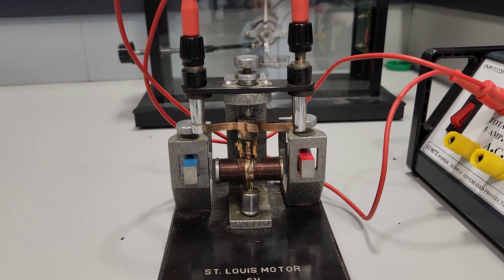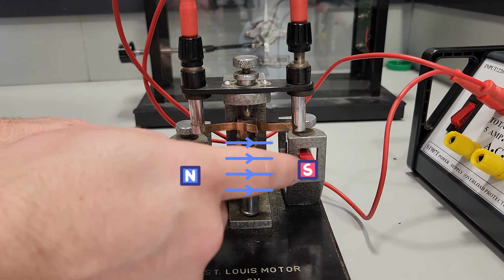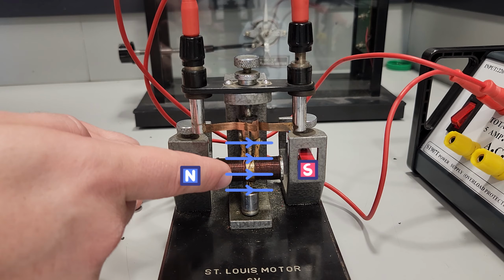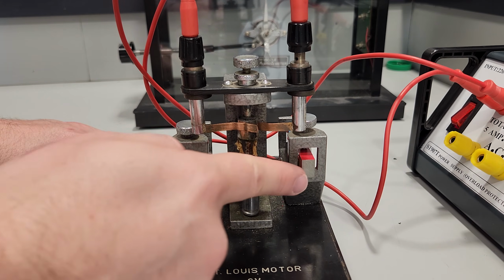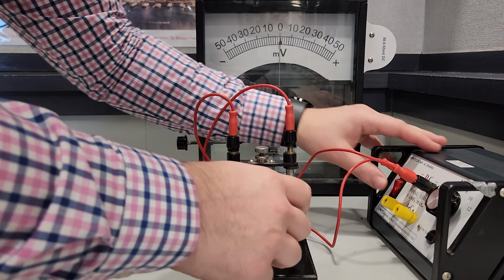This is a simple motor. As current flows through the coil, it establishes a magnetic field. The permanent magnets interact with this field, producing a force that causes the coil to rotate. When the coil reaches halfway, a slotted conductive ring is designed to reverse the current, which reverses the field in the coil, reversing the forces, allowing the coil to continue in the same direction, and so on.